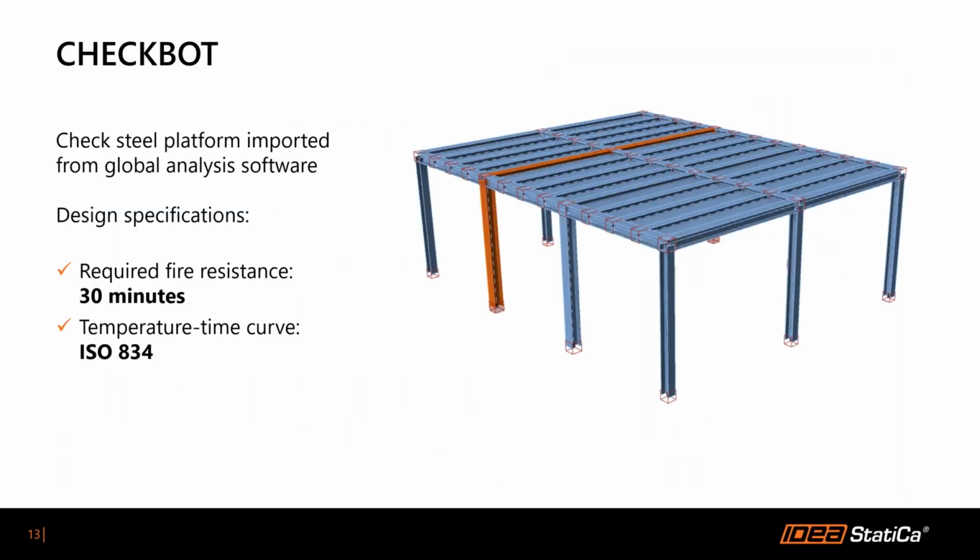For our worked examples, I will be using a simple fictional structure that was created in a global analysis software. And this is basically a steel platform that's supported on two main steel frames. In the global analysis software, the structure was fully designed under ULS and SLS loads, and it was also assessed under the fire design situation.